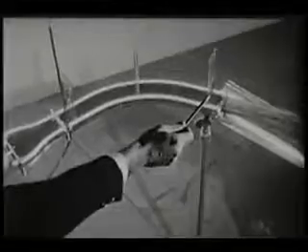This is a set of 3 static pressure manometers in the straight section approaching the bend. This set is in the middle of the bend, and this set in the straight section following the bend. In the upstream straight section, the streamlines are virtually straight, and the 3 manometers show no pressure variation normal to the streamlines.